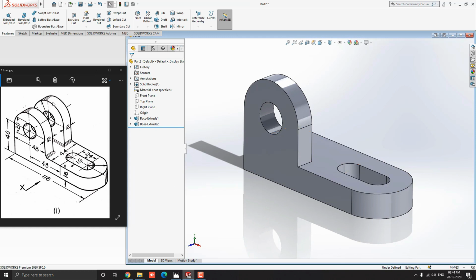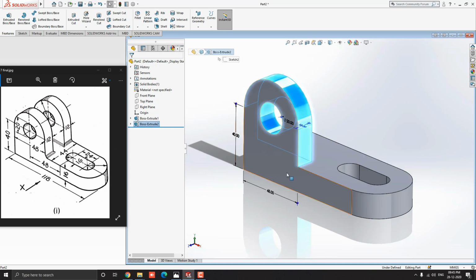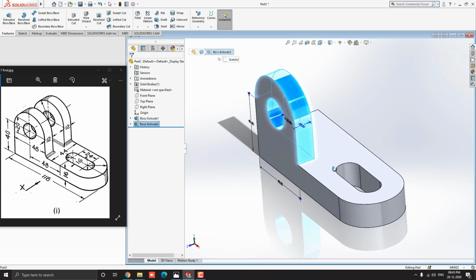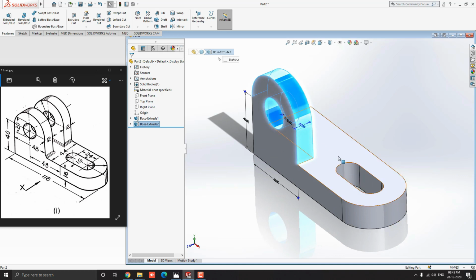For this second solid, we need to mirror the recent solid step. We have to mirror on this side. Select this last created step from the design tree. See the highlighted object. We require the mirror reference at the middle of the object.